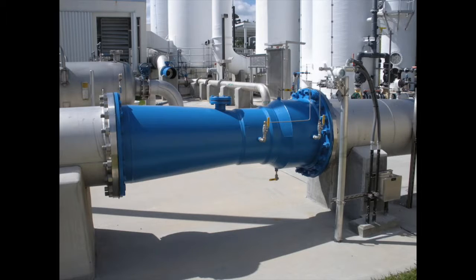Some of the advantages for the venturi meters are that they have less chance of becoming clogged with sediments, the behavior can be perfectly predicted, and they are able to be installed vertically, horizontally, or inclined. Some disadvantages are that they have an expensive initial cost, they are large in size, and maintenance of the meters is not easy.